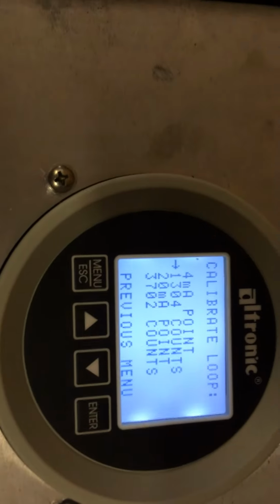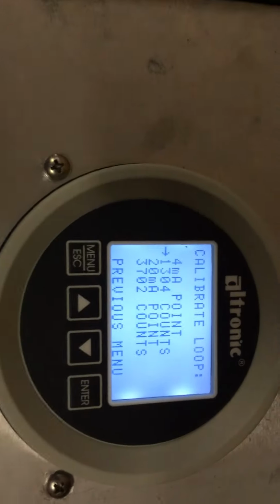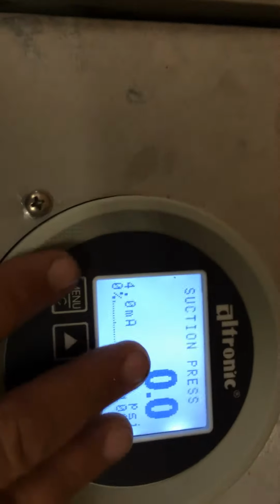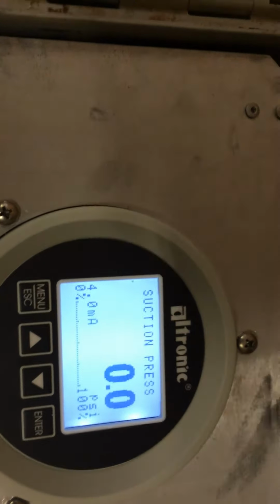So your unit's running, loaded, in manual. Switch it to auto, and at the same time, watch your MIDS panel screen on the key engine data. You can see the actual RPM and the desired RPM. Now the desired RPM is going to change much faster. So for example, let's say your minimum run speed with this gauge, you want it at 1000 RPM.